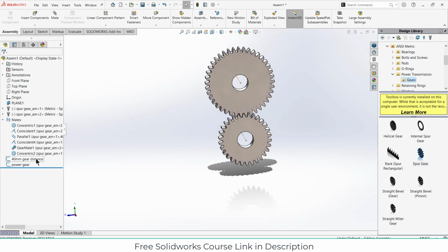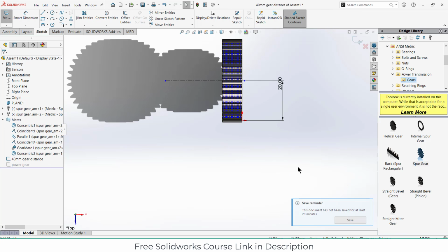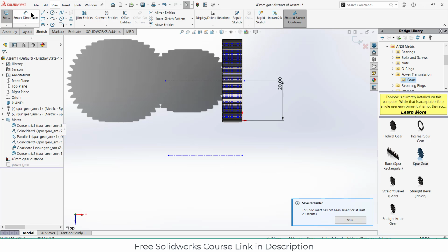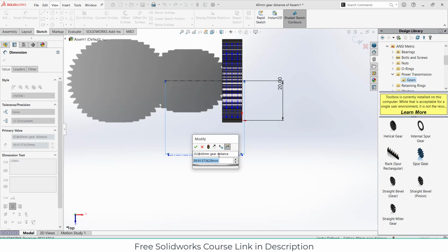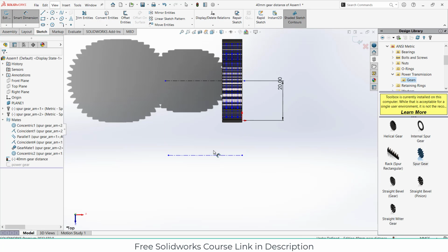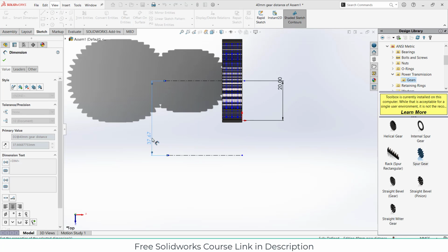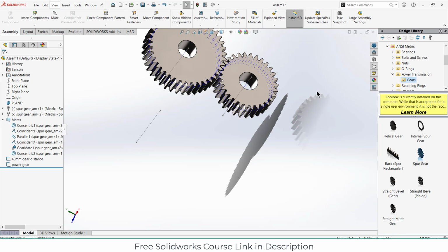Okay, so select the sketch, click on sketch again, but this time the distance is greater than 20. It is 20, sorry, it is going to be 20, not greater than. Or you can just cancel it, delete this, 40, click OK and exit the sketch mode.